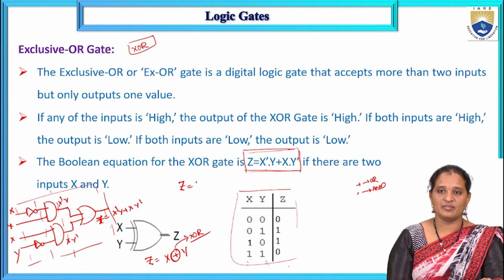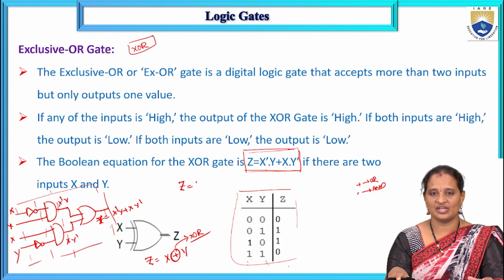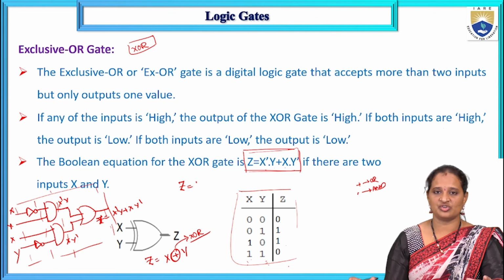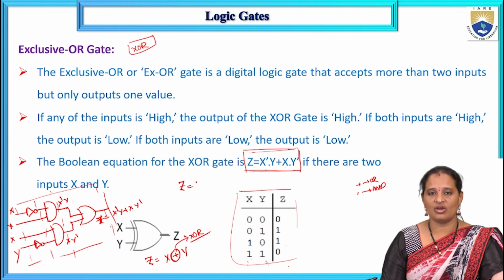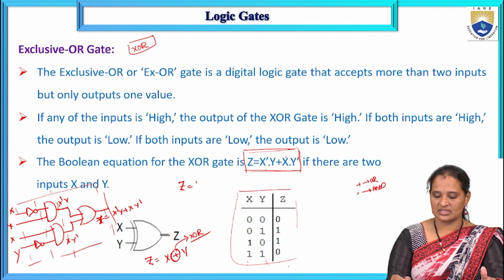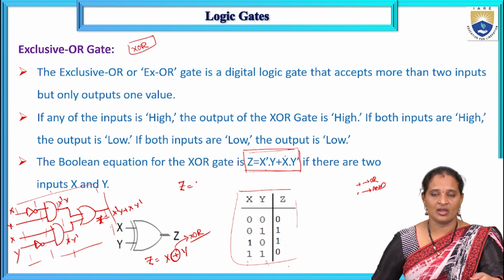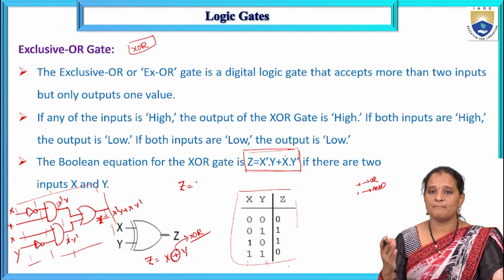So any other Boolean function which is a multi-level implementation can be done with the implementation procedure of NAND and NOR logic. We have to realize them using NAND or NOR gates. That is why I am not discussing XOR and XNOR here, which come under multi-level NAND or NOR implementation. I hope it is clear why I am calling it multi-level, because the output of one logic gate is again given as the input to the other logic gate in the same circuit.